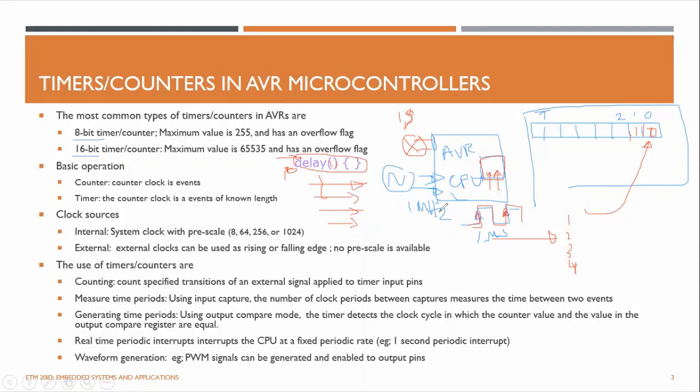There are some other sensors connected to the microcontroller, maybe sensor 1 and sensor 2. Sometimes these need some service, right? So the CPU sometimes misses these events in communicating to them, because it's just being busy inside this delay function. It is not doing anything and just being busy until this time duration ends. So that's one disadvantage of using a delay function.